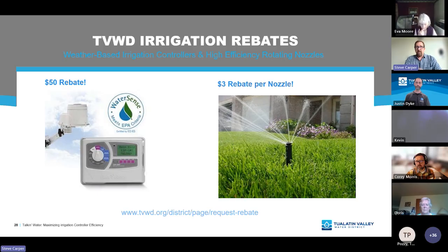The Beehive. The reason I went with the Beehive model is I also have what's called a Flume meter monitoring device. It's a device that attaches to my meter until City of Beaverton installs an AMI, which I'm pretty excited about, which is basically a smart water meter that's going to have really great, like 15-minute meter reading resolution. We don't quite have that yet. So right now I have a device on my meter that basically measures the water flowing through there every 5 seconds. And then it connects to my Wi-Fi. It sends me alerts if I have any constant flow or anything that might give a leak signal, a leak indicator.